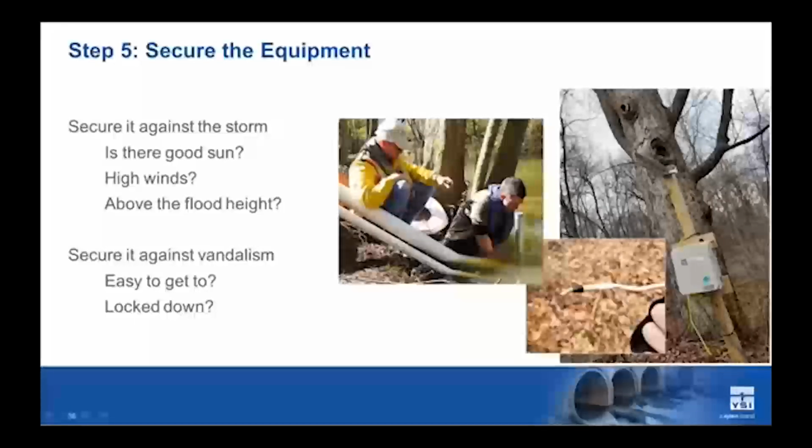Another thing is we think of placing a sensor like a radar above the height of the water, sometimes not even considering how much that height is going to change during a stormwater situation. If you have any historical data about the flood levels at a site, it's really good to use that in placing your sensors. And then another thing, and this came to us from some colleagues at Grace College who did a great webinar with us earlier in the year, securing your site against vandalism to the extent that's possible.